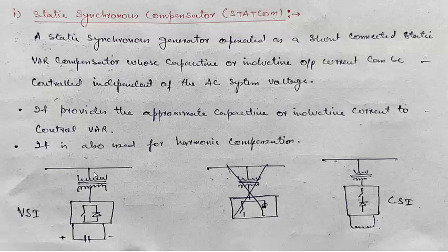That is done by the control, and that part we will be discussing in the coming chapters, in which we will discuss the static synchronous compensator. But I just want to make sure you understand that we don't have an actual inductor and actual capacitor to do the actual thing. We have only the effect of the capacitor or inductor.